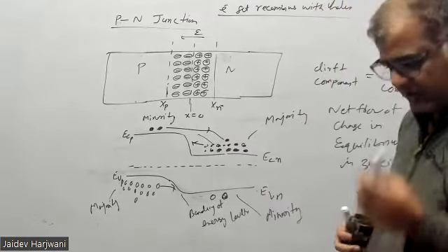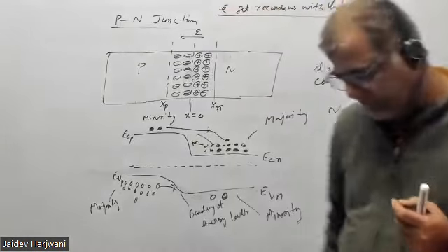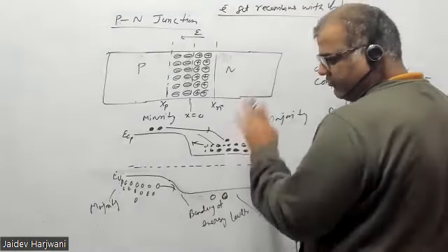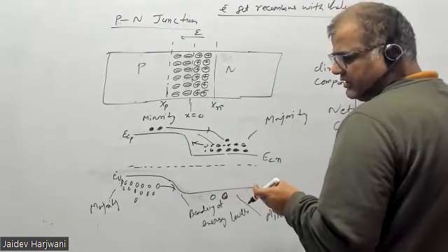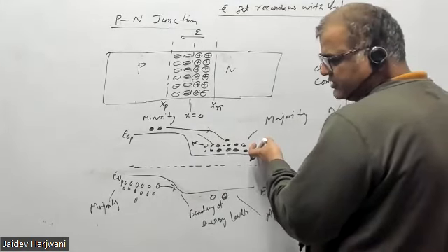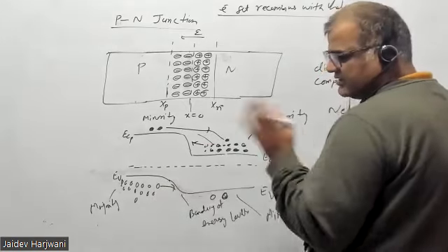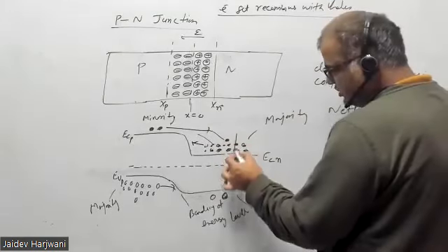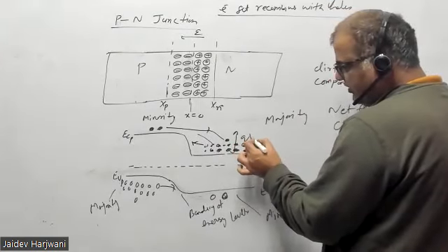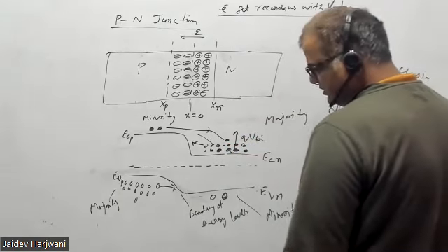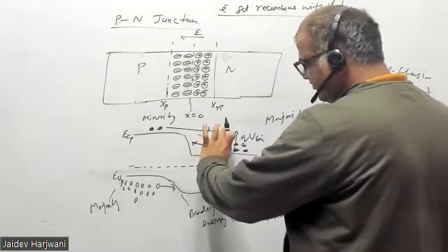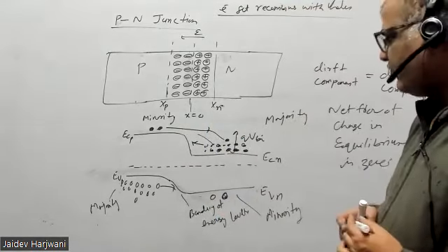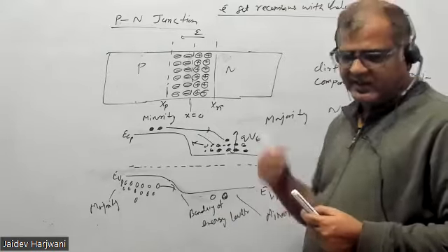Okay. Now what I want for diode here. Basically your diode is a PN junction, and once your PN junction is formed, even though electrons are there as majority charge carriers here and holes are present as majority charge carriers here, still there is no current without any force, because there is a potential barrier. This is called qVbi. There is a potential difference. A barrier arises. Because of this barrier, no current can flow in a PN junction without an external field.